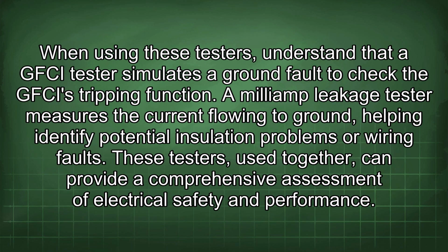When using these testers, understand that a GFCI tester simulates a ground fault to check the GFCI's tripping function. A milliamp leakage tester measures the current flowing to ground, helping identify potential insulation problems or wiring faults. These testers, used together, can provide a comprehensive assessment of electrical safety and performance.